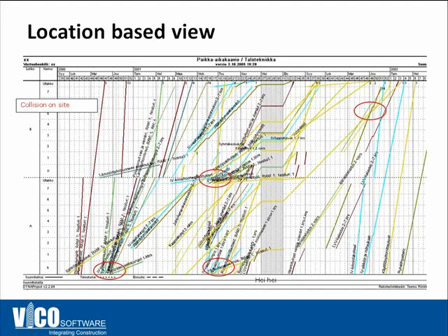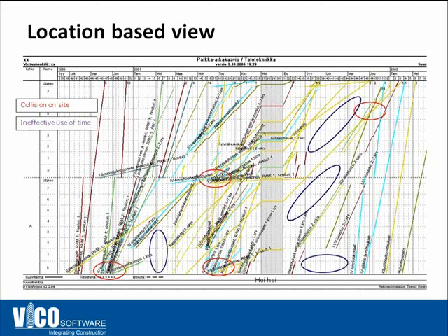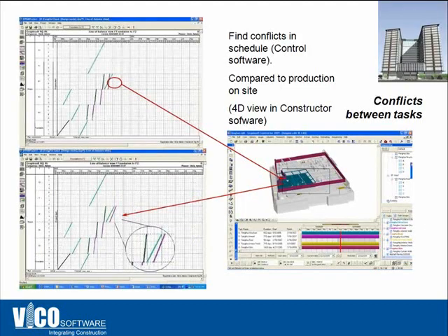You can start optimizing the schedule also by identifying the areas that are underutilized and making sure that your production rate and the various crews are progressing through the site, through the construction zones, at a parallel, similar pace. When the schedule is linked to a model, you'll be able to analyze constructability, and as I said earlier, if the framing's not finished yet, but you're ready to build the drywall, you have a problem, and that's very easy to visualize in different views of the model and the schedule itself as well.